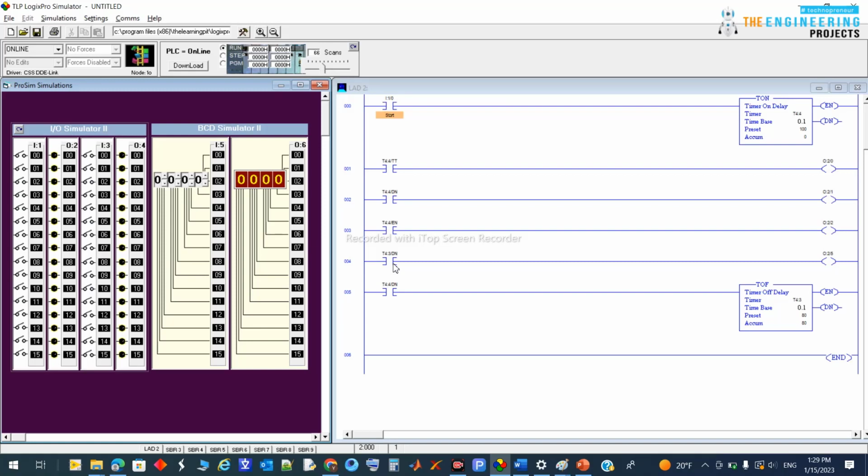So I keep counting or calculating the operating time of this machine until I reach the desired preset value, which is the duration you set for maintenance. And then I can make an alarm or indicator to show the operator that, for your machine, now it's time to make maintenance, or change oil, or replace one part, something like this. So that kind of timer is very important, and we call it the retentive timer.